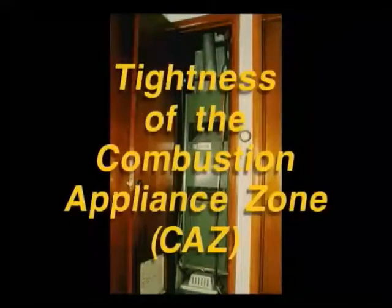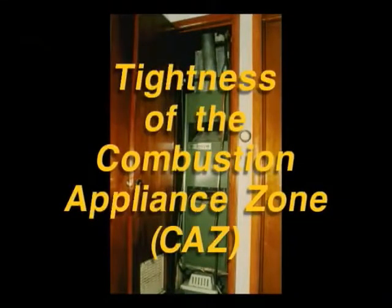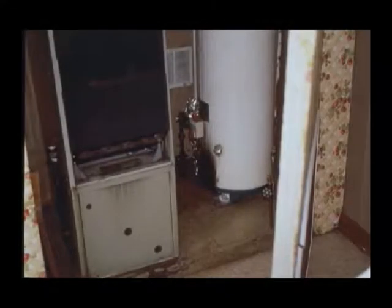Tightness of the combustion appliance zone. In theory, if an appliance is in a tight enclosed space and does not have intentional combustion and ventilation air openings, it can starve for air and draft will be affected. This is the reasoning behind code requirements for adequate combustion air openings. While codes have required this, in most cases when there is a downdraft or spillage problem, it is due to depressurization or venting issues rather than air starvation. And air starvation is often a misnomer.